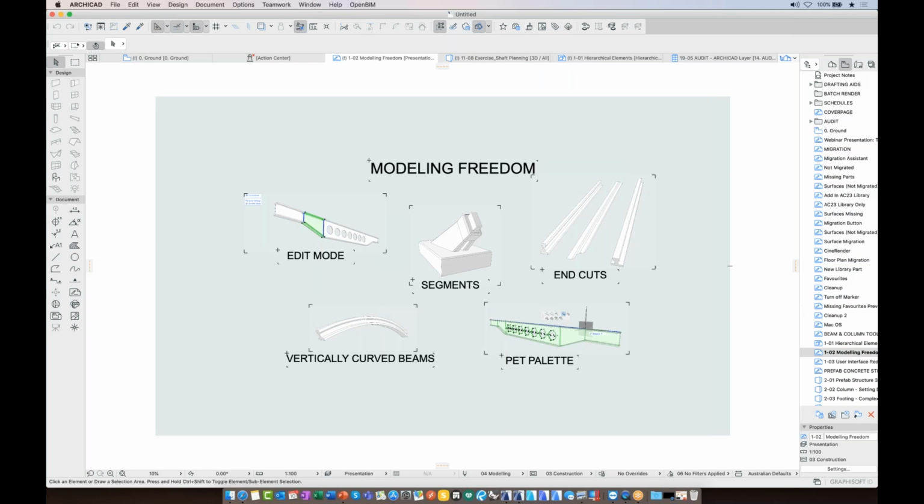We're utilizing things that we're already familiar with, like edit mode from the stair tool, the curtain wall tool, the railing tool, to select sub-elements and make adjustments as if they were normal things in Archicad. You can see the little black hotspots and the profile modifier lines here. We're breaking things down into segments so that we can start building up complex geometries by creating little parts.